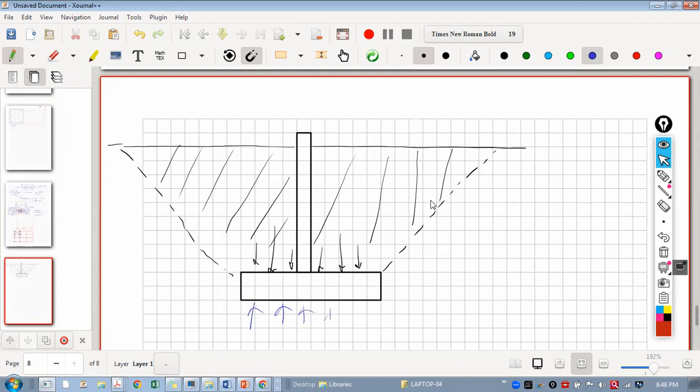This also you can take. I think this criteria is given in the American code, ACI code. You just draw this angle of repose as given in the Geotech report and then you can take. Or, as a conservative approach, you will think of this first, simple. And if it does not pass, then use this, because this additional is always there.